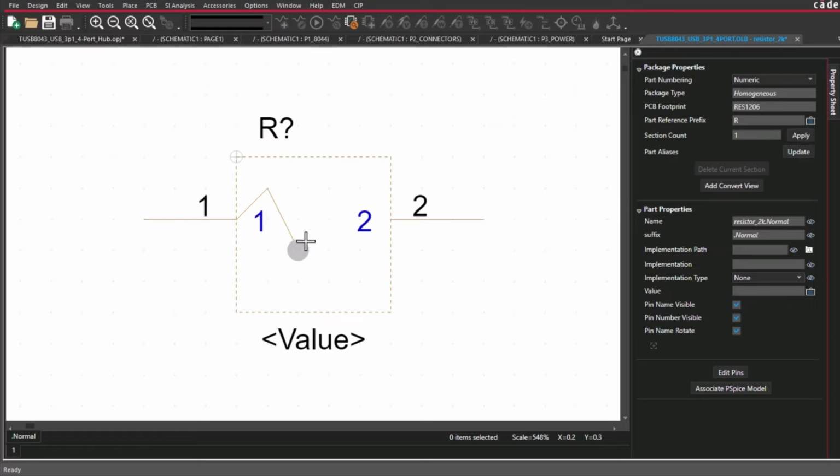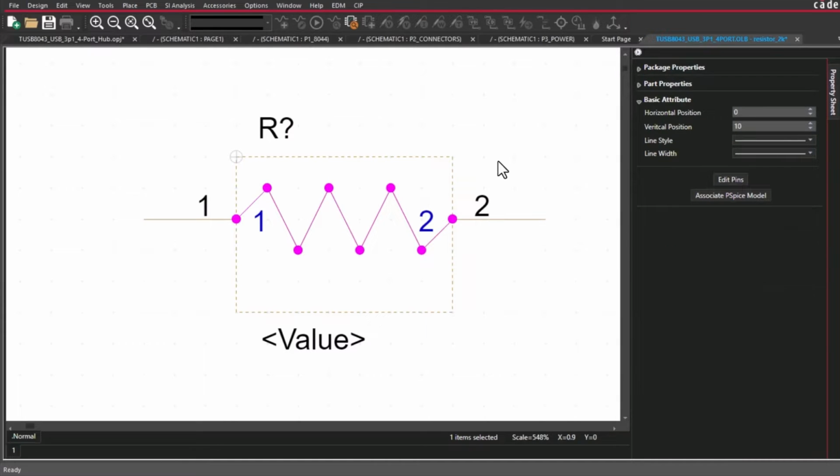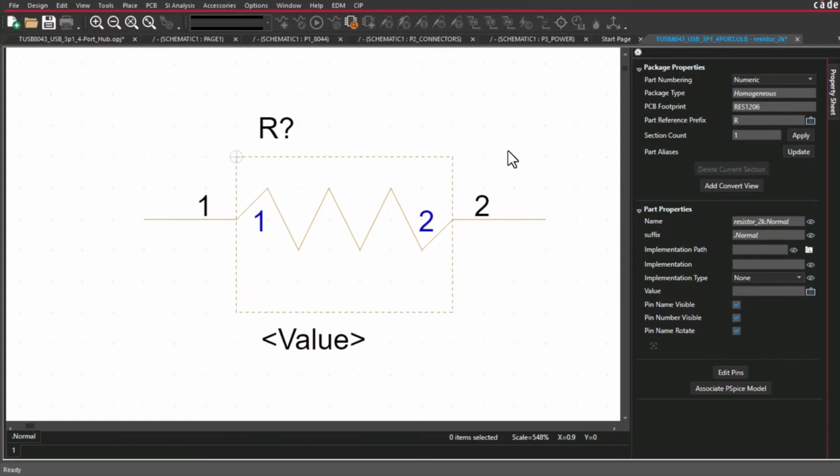You then have the SPICE model to simulate the circuit behavior within that same design. It's like running code for that part to make sure it works the way it's intended according to the datasheet. You also then have IBIS models. IBIS stands for Input-Output Buffer Information System. So this is a model to simulate behavior in response to changes in design frequency and temperatures.